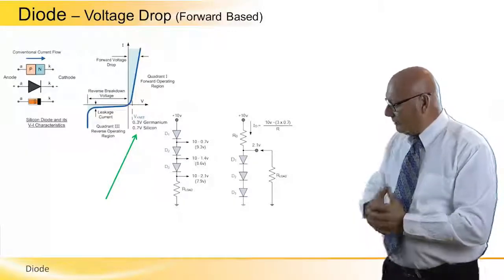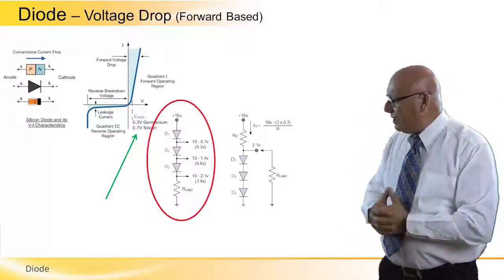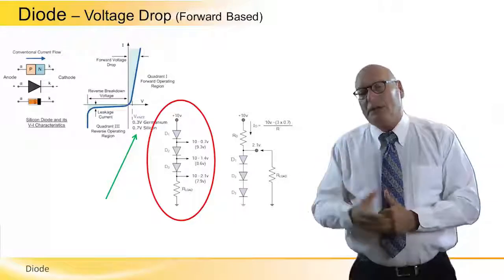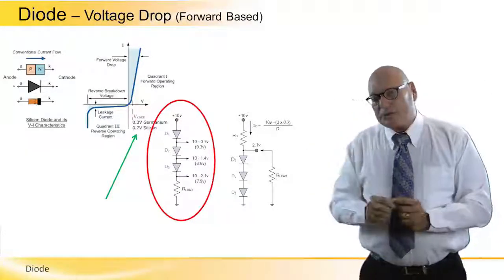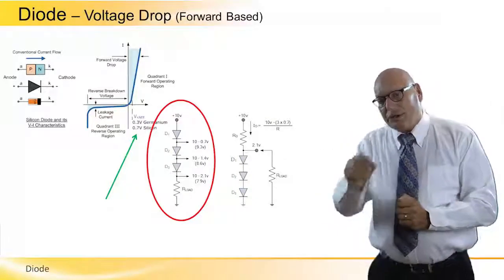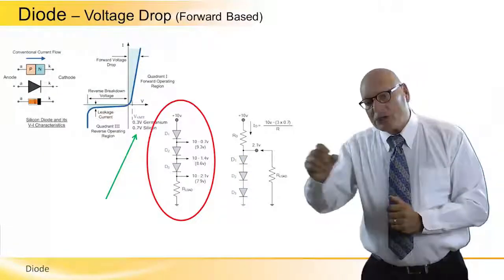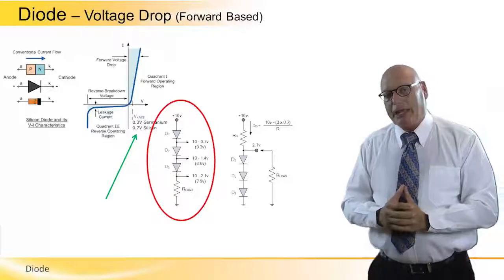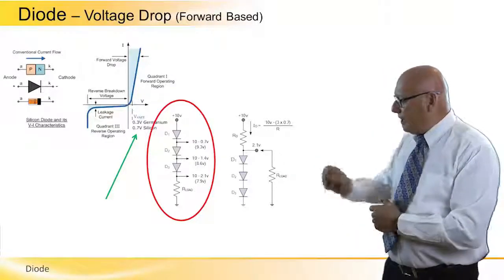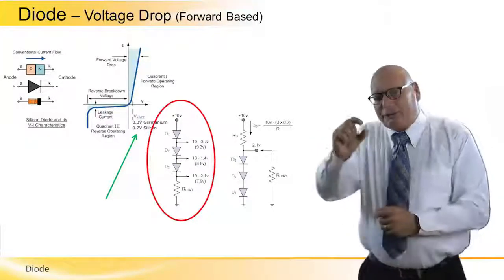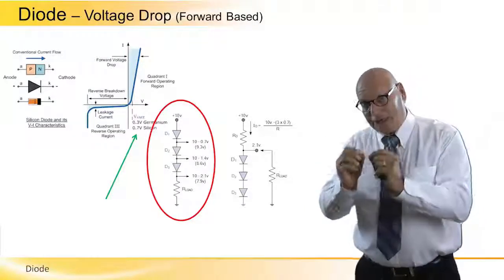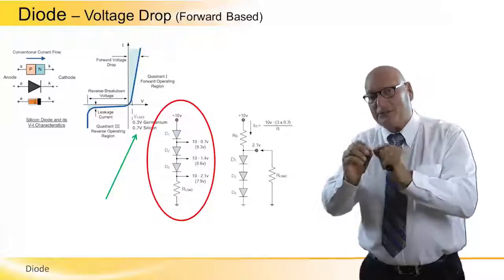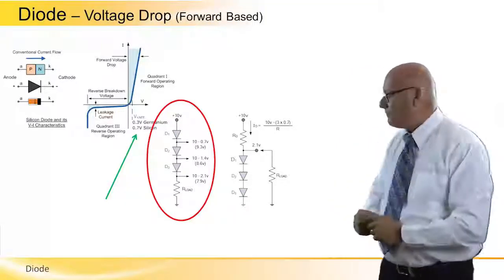On the second picture from the right, we see 3 diodes. They are still in series, but we take outputs of different voltages from each branch. We branch out 3 times. Again, when we branch out 3 times, every single diode takes 0.7 volt in order to conduct, and it's a fixed level of voltage. It's a fixed number, 0.7 in silicon.